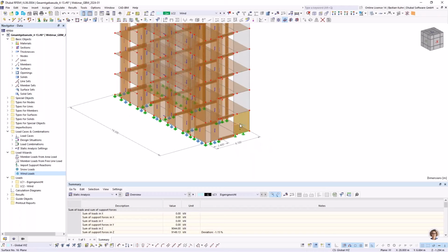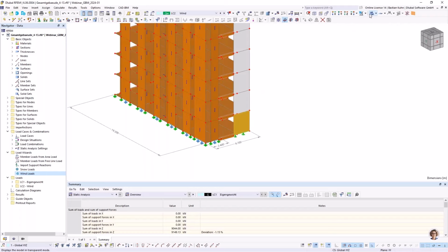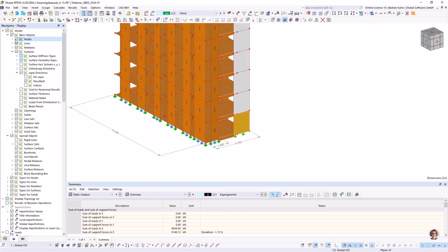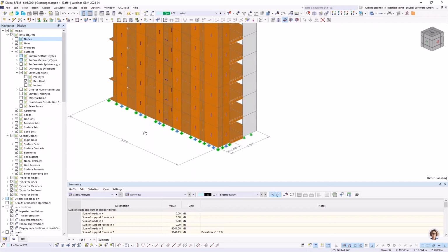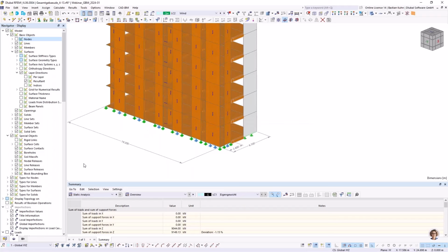I mentioned it. Take a look at the slab or at the walls. Slabs we did. Maybe if I put this on and we can get rid of the node, it's looking a little bit better. The stiffness direction, I don't know if you saw that when I mentioned it on the ground. I have an option for the CLT plates to show the resulting stiffness, and usually walls in CLT plates, you always put the stiffness direction vertical, and on slabs, you put it horizontal. That's what this blue check should tell you.